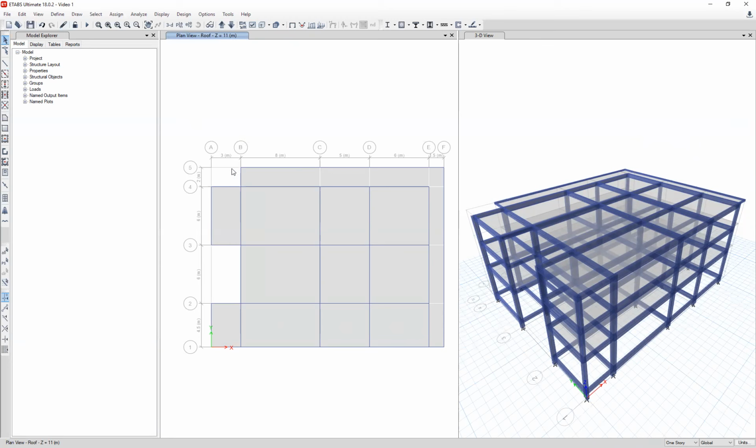To do this, we have to select the beams where we put the loads. So for the roof, let's assume that our loads will be at the perimeter of the building and will be like a 1 meter height wall. For that one, you have to calculate the self weight of such wall. And let's assume it is 4 or 5 kilonewton per meter.